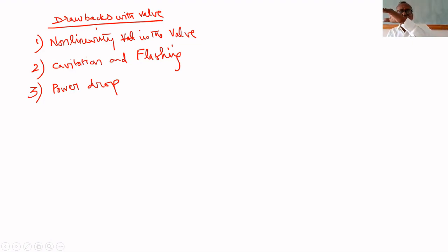Let us assume that the tank has to be filled for 5 feet. If you design a valve and open 100%, it fills for 5 feet, which means you could always open the valve 100%. Why are we always opening 50%? To maintain constant flow. If you open more, you can design a smaller valve and keep it 100% open. Why 50%?